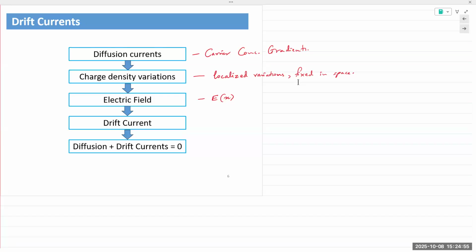In fabrication terms, we can accurately predict how deep our junction would be. Remember, in fabrication, the process of introducing impurity atoms is either diffusion or ion implantation. Diffusion is simply heating it up, so it diffuses into the material. So we don't know how far it's going to go unless we calculate that, right?